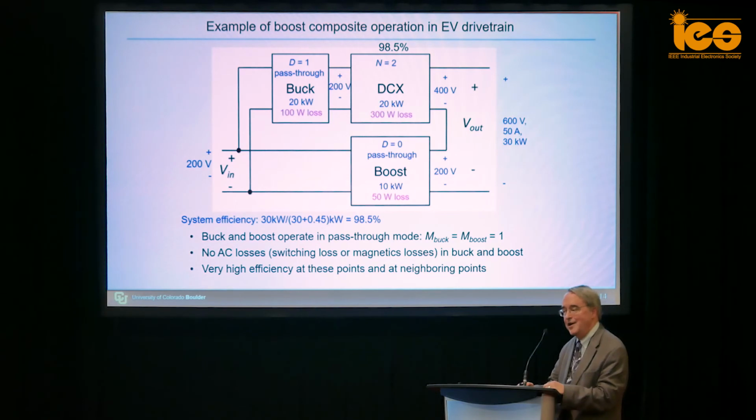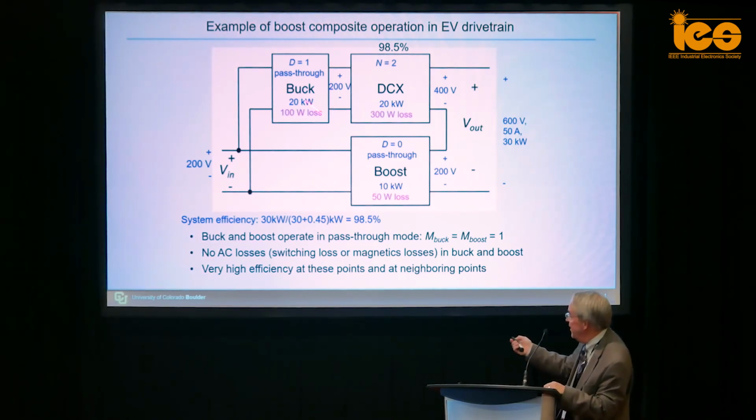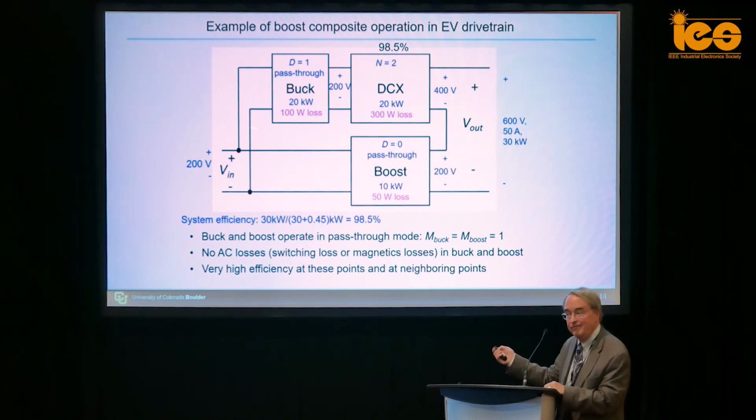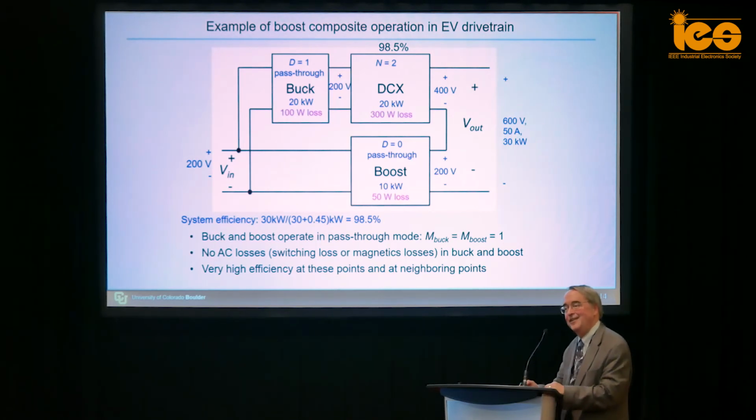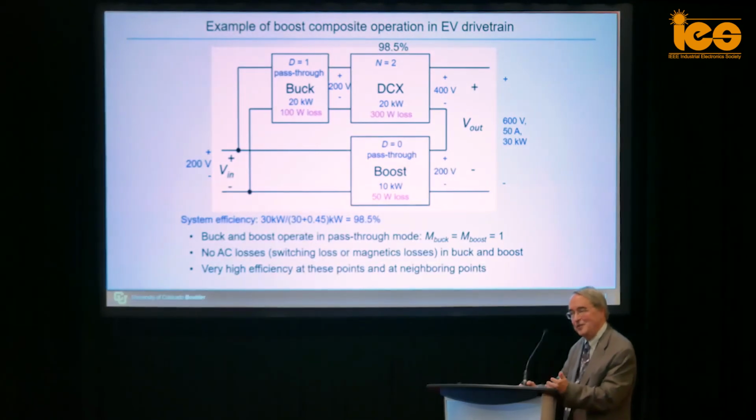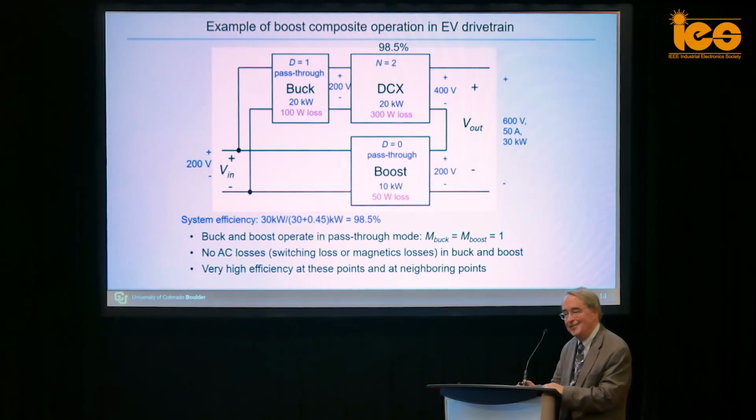Is that true? Right. The turns ratio is the biggest choice to optimize, but the values of the inductances affect when these converters have zero voltage switching and not, and how big the ripples are. Those are things that can be optimized also.